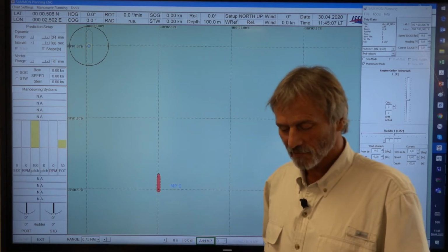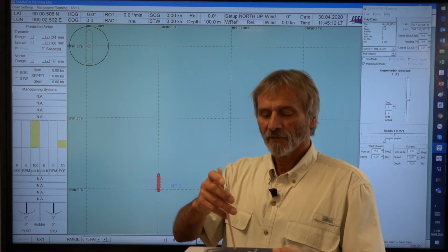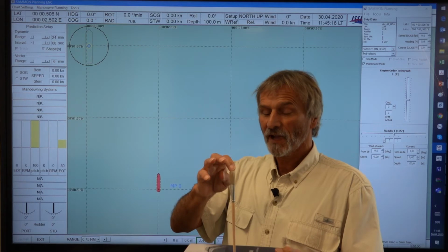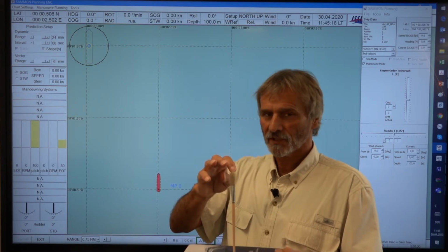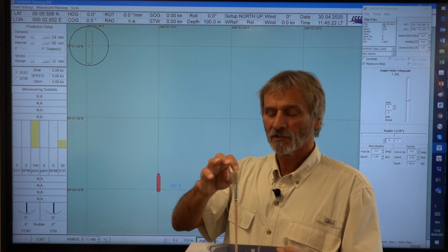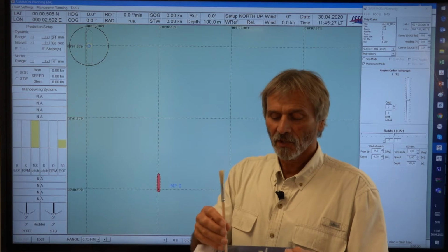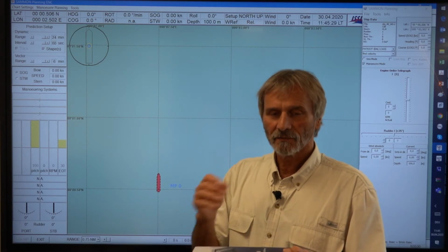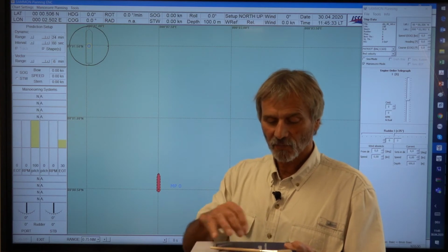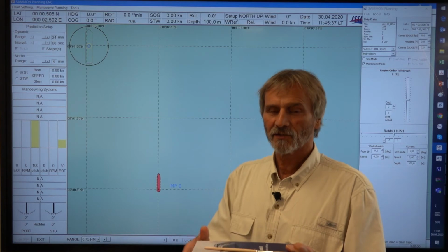So, for instance, this brush, if I try to balance this brush upright, I need to find the equilibrium, because stability is always addressed to the equilibrium condition. And if I let it go, it falls down. So it's highly unstable. And it falls until it's in this position. Is that a stable position? Yeah, it is. Because if I change it a little bit, it always goes back into stability.